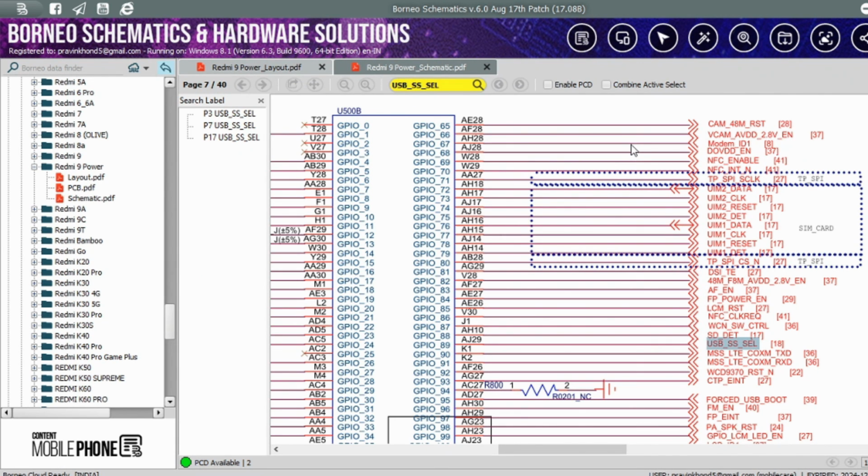After this, I already explained in the block diagram how OTG power is obtained when you connect the charger on the charging line. When you connect the charger, your phone runs in charger mode. The DC to DC IC or PMI makes VPH through the charging line or VBUS line, and also gives some power to the battery through a MOSFET. After enabling OTG, the MOSFET works in reverse. It takes the power from the battery and also gives it to the VPH.